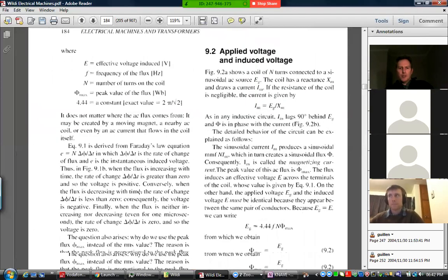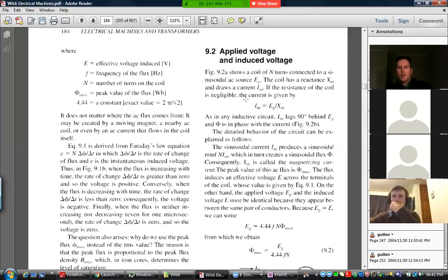What else is important? Okay, resistance of the coil. Typically the coil resistance is a lot smaller than the reactance. So we're dealing with the sine wave thing. As soon as we've got AC in the mix, we mustn't consider just resistance. We need to know impedance because of the inductance, because it's a coil, and not just a coil, in fact, but a coil with a nice magnetic core, which makes its inductance even higher.